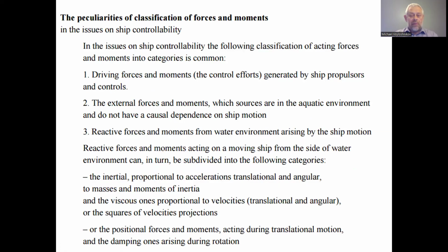The peculiarity classification of force and moments in the issues of ship controllability. When considering the ship under controls, we have a slightly different classification of the forces acting on the ship. In the issues of ship controllability, the following classification of acting forces and moments into categories is common. The first category is driving force and moment, the control efforts generated by ship propulsors and controls.